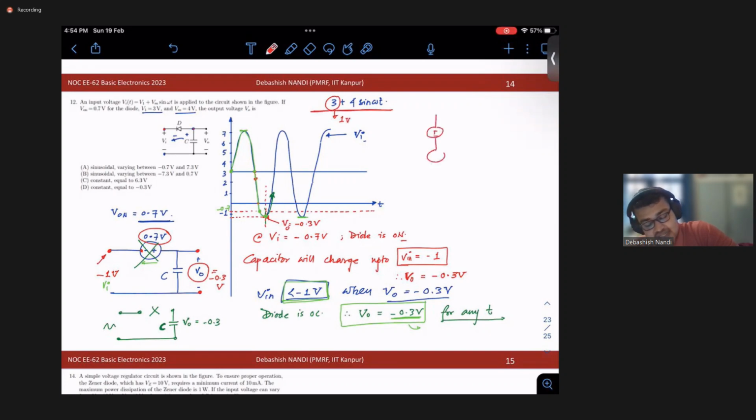If you see in any circuit lab, you will have a power supply or some battery, and in series you connect it with a signal generator input. You go to any circuit lab of your college and check how the signal generator looks. It can give you sinusoidal input, triangular input, ramp input. So this signal generator is in series with this. If I reduce this battery voltage, then my DC level will come down.